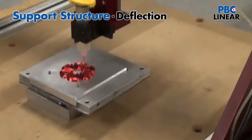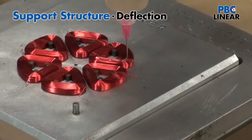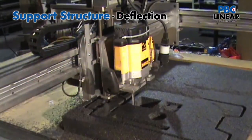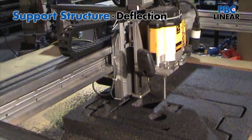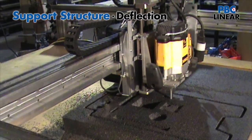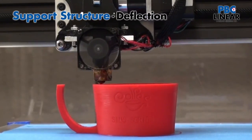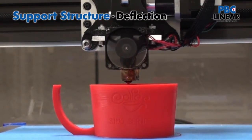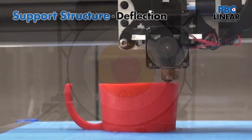Keep in mind that various types of applications have different requirements. It may be that a wider range of deflection is acceptable if the motion is slow and there is adequate settling time to account for location. In higher speed applications, it may be necessary to increase the rigidity of the system to shorten the settling time and meet the repeatable positioning required.